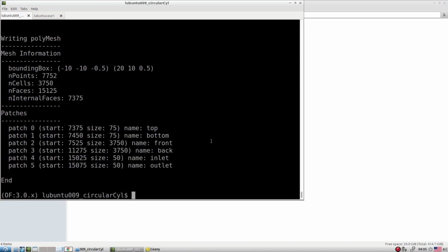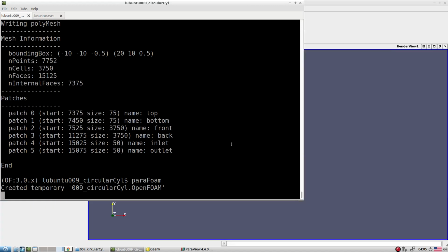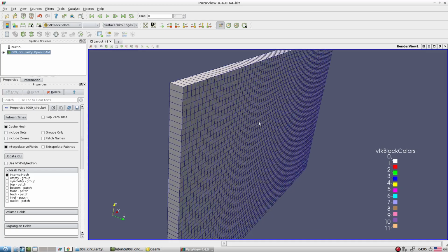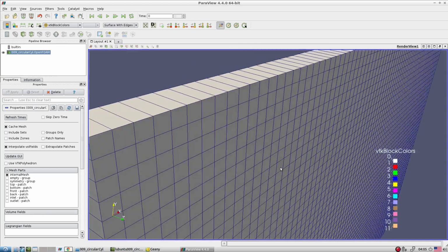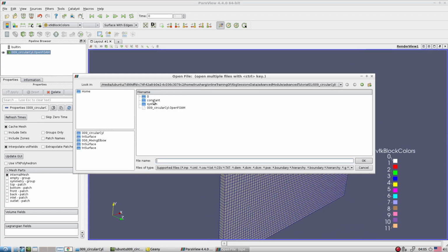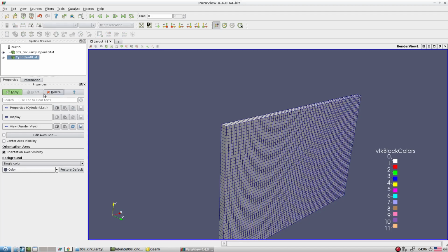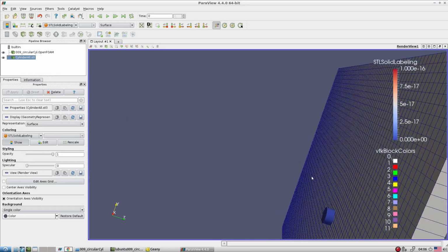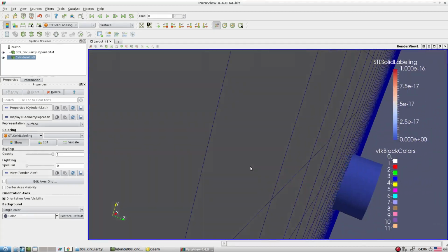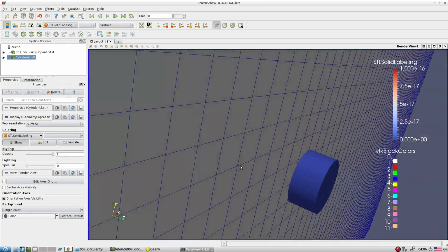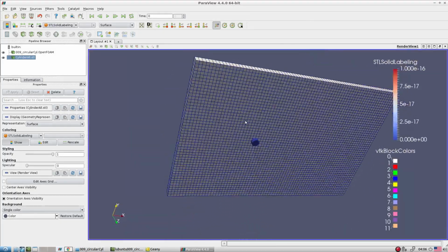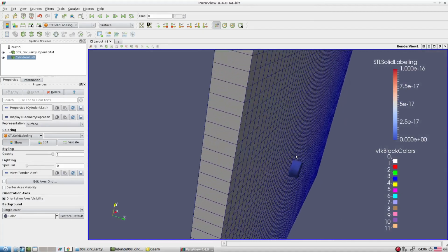And show you the blockMesh. If you look here in the blockMesh, in the Z direction I gave only one element. Let's open our surface so you will understand. Look, our cylinder is not completely covered by the block; the block is cutting this cylinder. Whenever you require the two-dimensional mesh, this is the approach. Whatever the obstacle is, try to cut through that particular domain.